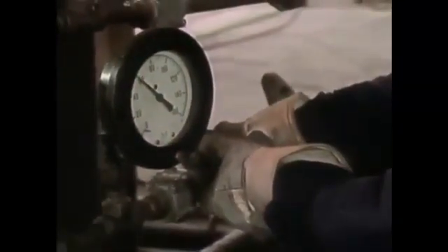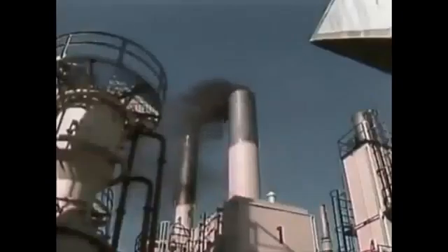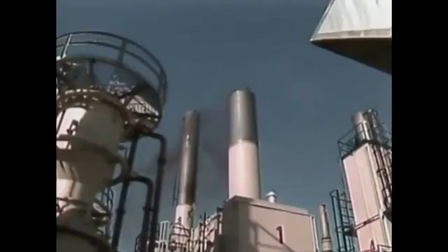If the fuel pressure is too high for the amount of atomizing steam and combustion air that's supplied, the result could be unburned fuel oil. This shows up as a smoky, hazy firebox and smoke coming from the stack. This problem is typically corrected by decreasing fuel oil pressure or increasing steam or air to the atomizer.